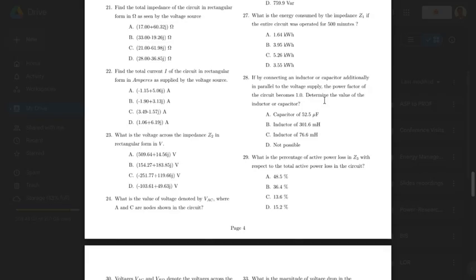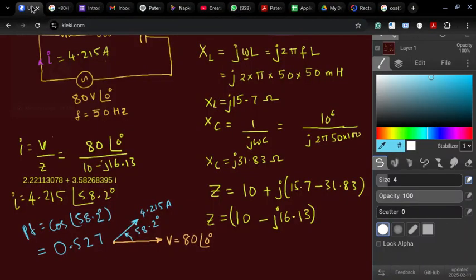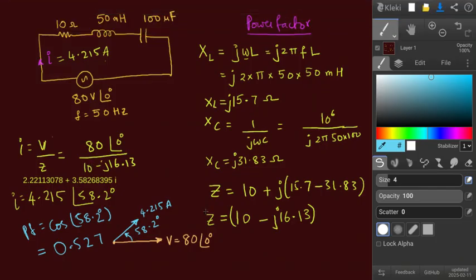In this case, you look at the diagram here. Here we say current is leading the voltage. This is an important point. The current is leading the voltage because if I stand here and look at the phasor diagram, first the current would be going, because all these phasors are assumed to be rotating in the anti-clockwise direction. So current is leading and voltage is following the current. Therefore the total circuit is capacitive in nature.